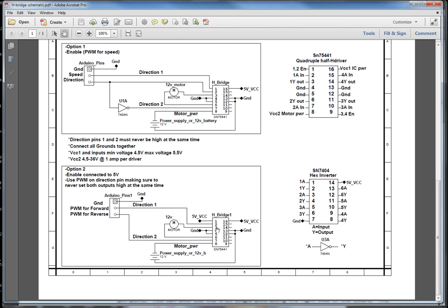So what we can do is maybe use a 10 kilo ohm pull down resistor. Like with the input pins in the Arduino, we frequently use a pull up. You set the pin mode and do an input pull up, but we want to keep these pins low unless they're actually getting a signal from the Arduino board to turn them on. So we would use maybe a 10 kilo ohm resistor and pull them to ground, both 2 and 7.